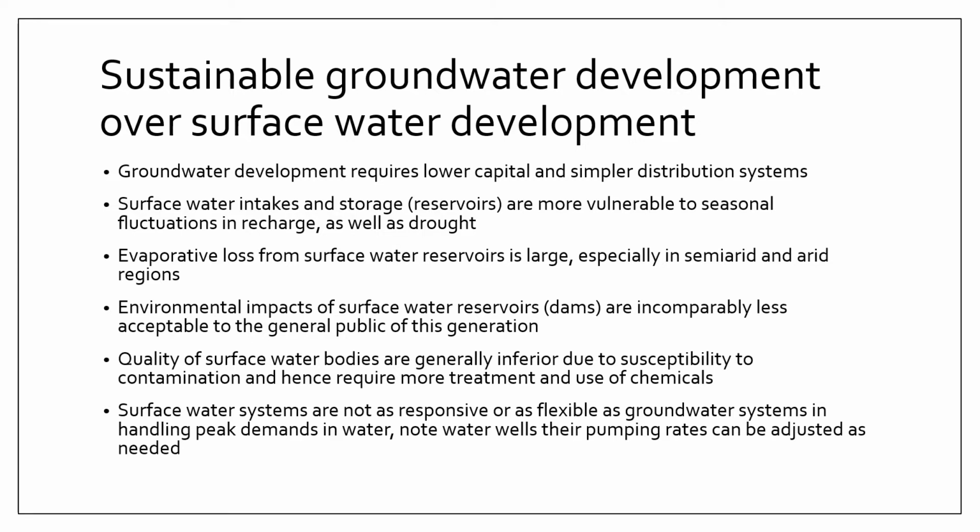First is normally groundwater development. Water wells and spring boxes are typically much cheaper to develop compared to water reservoirs. But of course, water reservoirs involve much larger capacity. But in terms of initial investment, groundwater projects typically involve smaller amounts of capital.